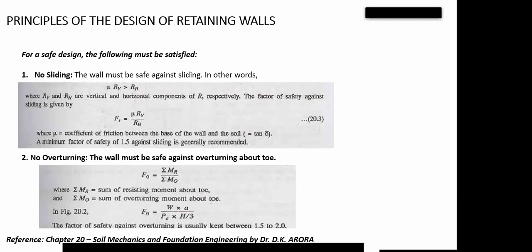if you only have your active earth pressure acting on it, once you find the lateral pressure, that is Ka gamma H, that is what will be causing the overturning. Just take that one, find the resultant force, then take the moment about the toe. The moment about the toe will be the force times H over 3. We are going to see diagrammatically soon. So what will be responsible for your overturning moment alone, for OBJ purpose? Please note, it's only your horizontal component forces that are responsible for your overturning moment.